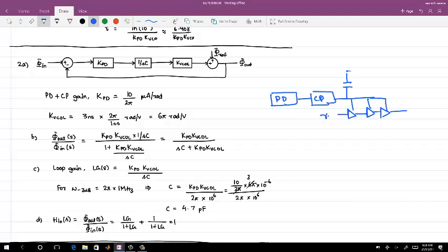So this is the reference voltage, and this is the input and output. I think the only problem might be to define the control voltage. If T delay is 1 nanosecond per volt, 1 nanosecond for one delay cell, then for 3 delay cells it should be 3 nanoseconds, right? If you change the control voltage, how did you change this delta T to output?